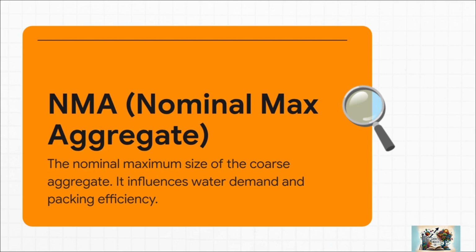NMA, it sounds complicated. It's not. It's just the nominal maximum aggregate size. In plain English, it's the size of your biggest rocks. And it matters because bigger rocks generally mean you need less water and sand to make a workable mix, and that changes the whole recipe.